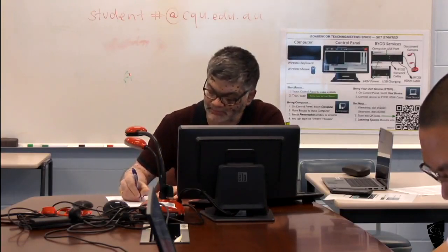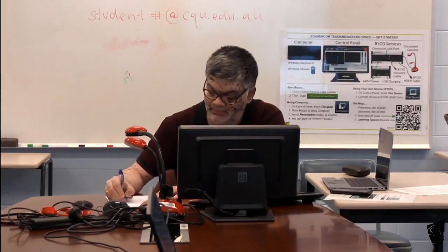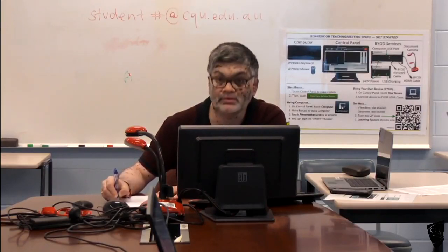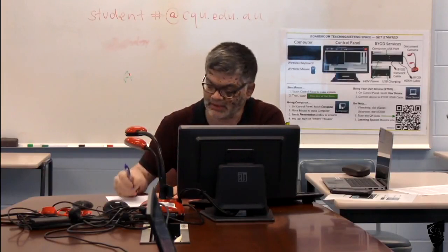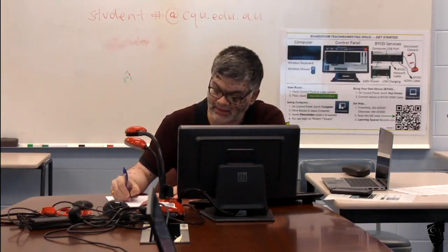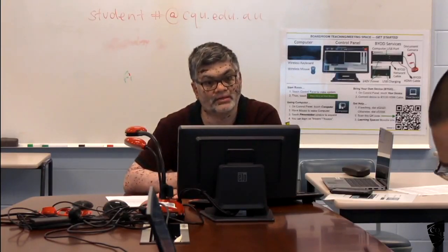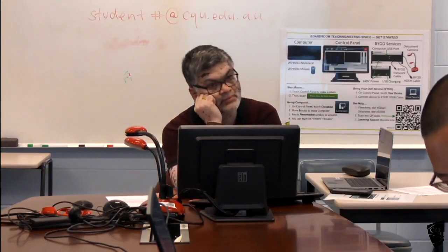For one-way slab, you use the same as continuous beam. So we did that one. So the same, you know that the wu ln squared upon some numbers. You remember this one? wu ln squared upon 16 or 9. So for different locations there are different numbers. So you should be able to get that one using the same clause. That is for one-way slab.